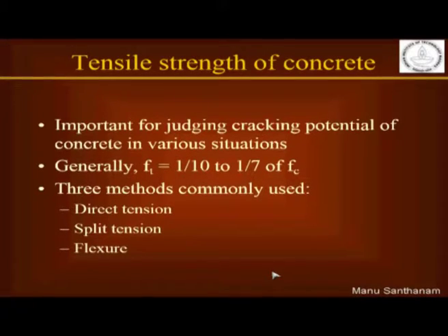that we consider to be not very important in the case of typical concrete structural element design, but when it comes to something like flooring or pavements, the tensile strength of concrete is also extremely important. And further, we need to understand the effects of shrinkage and creep, at what stage would they be able to cause cracking in the concrete? For that we need to get an estimate of the failure strength of concrete in tension.